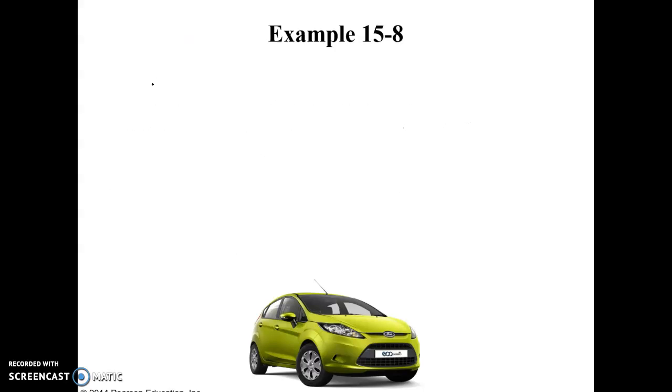Okay, so our efficiency is equal to the work being done compared to the heat that we put in. Okay, so if we wanted to solve this equation for the high heat, that's going to be equal to the work divided by the efficiency.